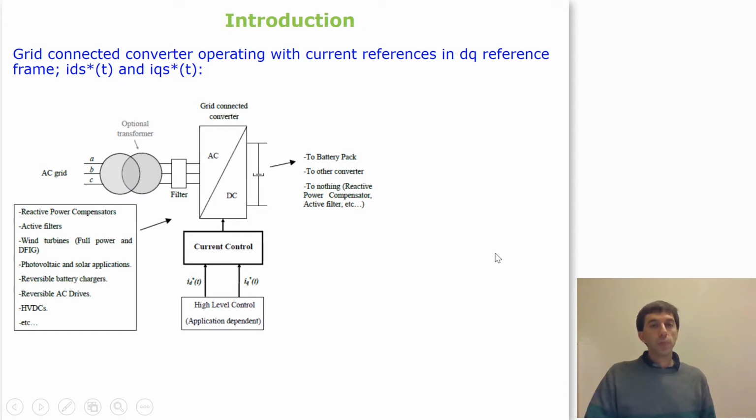So normally, in a power electronic converter which is connected to the grid, here we have the AC grid, that in this case we are going to focus on the 3-phase grid, which is the most typical one. Then we could have also a transformer. Not in all the previously mentioned applications we can find a transformer, but normally there is one. Then we have the filter, and this filter could have different topologies, but it is almost compulsory to have a filter between the transformer and the power electronic converter, where the semiconductors, IGBTs, diodes, and MOSFETs, and maybe others, could be placed. Here, the power electronic converter nowadays could have different topologies, like 2-level converters, 3-level converters, or even more level converters, and within them, different topologies.